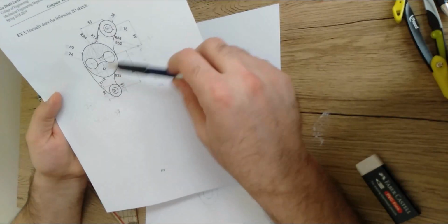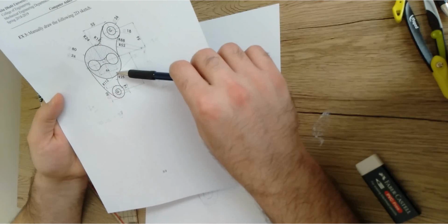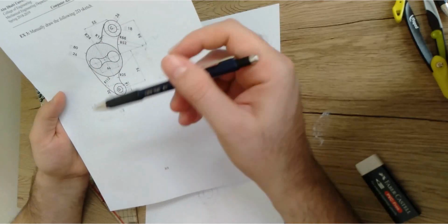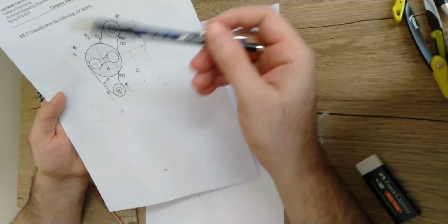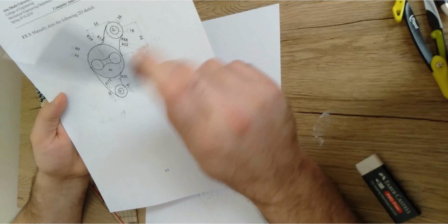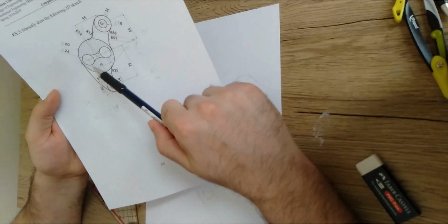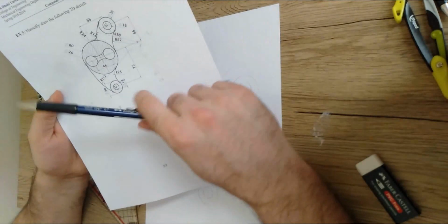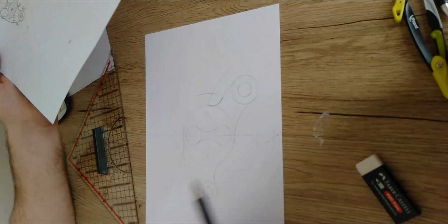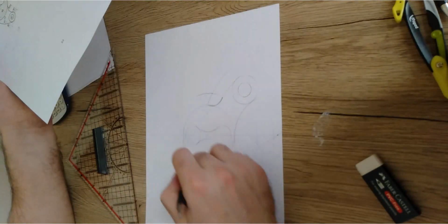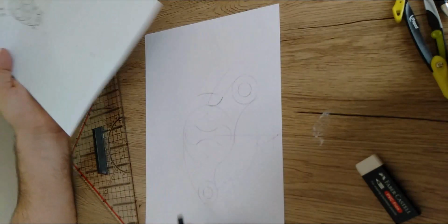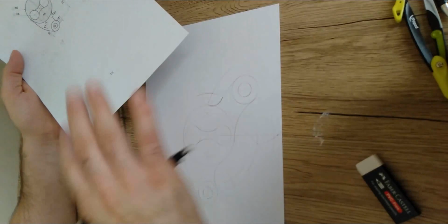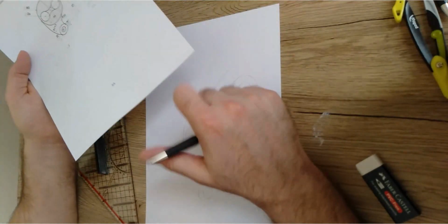And it is advised to use hard lead, or at least HB. So I'm just gonna draw this hatching with the 0.7. Another thing is that this hatching will not be finished. What does it mean? It means that, for example, as you can see, I've drawn some circles. Even this circle is not complete. This one is not complete. Why? Because at the end, I'm gonna go over the drawing to finish everything, right?